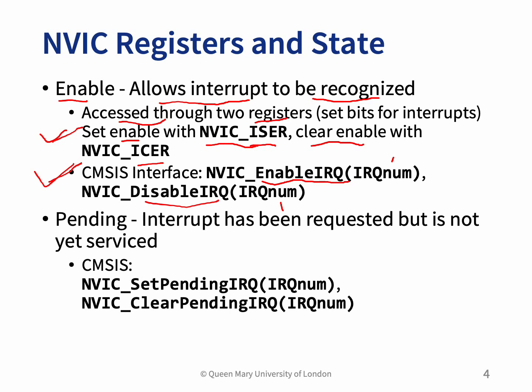Also, we can have the NVIC in the pending state, which is very interesting. We can initially assign an interrupt for a particular vector for the NVIC. So the interrupt has been requested, but we do not require it to run for the service. So priority is being set for the interrupt, but it's still pending. It's like it's on standby for becoming alive to provide the service required.